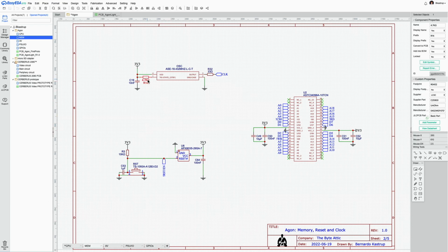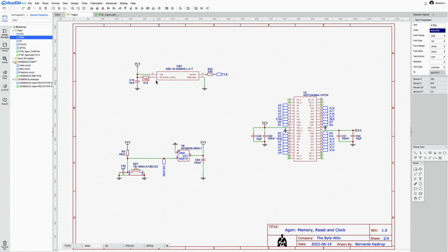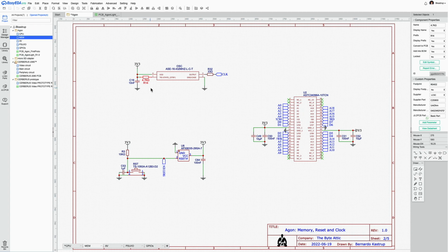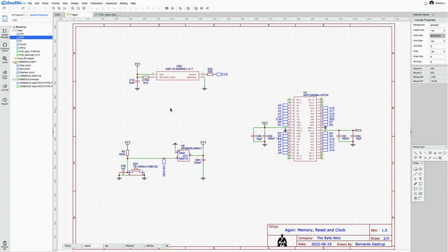This resistor here, you probably don't need it. It's basically just a pull-up resistor. You probably can connect 3.3 volts straight into this pin 1, because this has a very high input impedance. But just to be extra safe, put a current limiting pull-up in there. And this is just another bypass capacitor to even out the power signal, to keep it clean going into the oscillator.